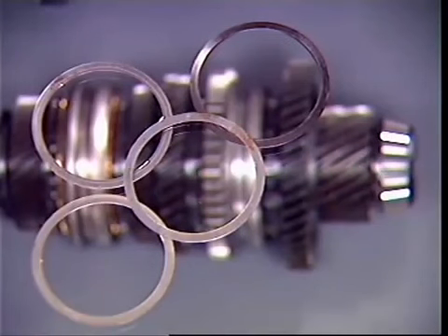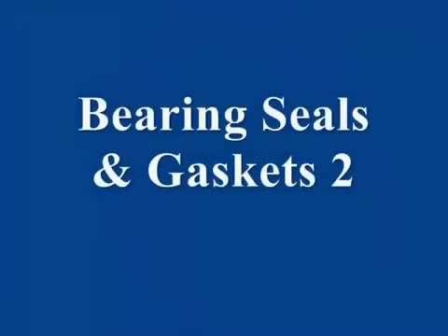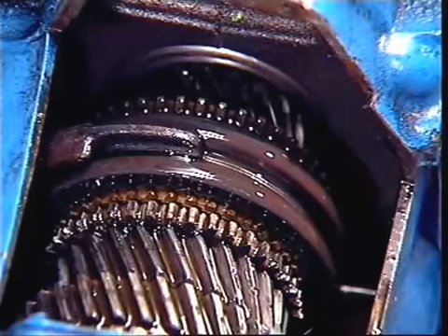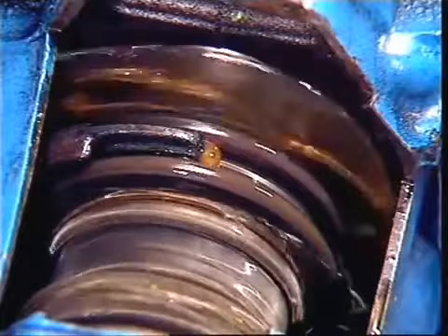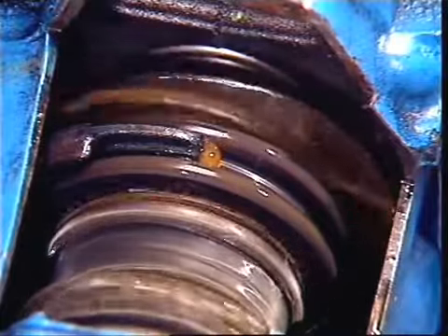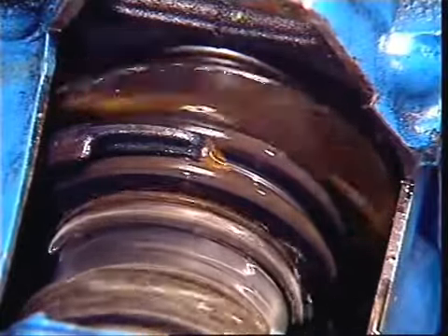Shims or selective washers can be used to provide for adjustment of preload. The bearings can be lubricated by being submerged in gear oil or by oil splashed about inside the casing.